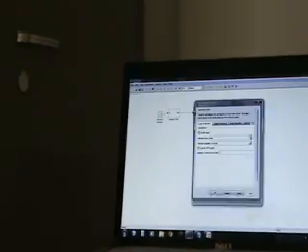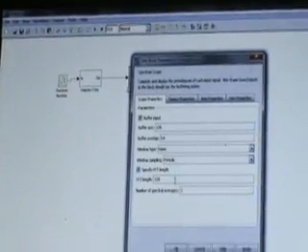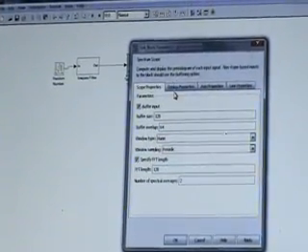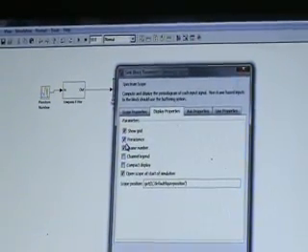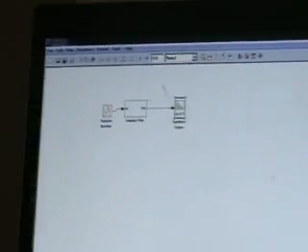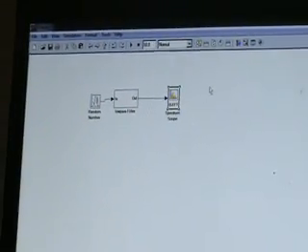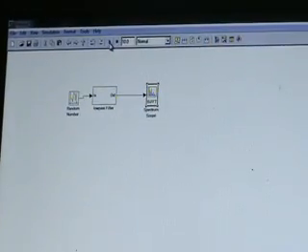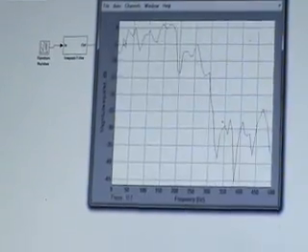Now in the spectrum scope we need to buffer the input, so we click on buffer input. We specify the FFT length, and these are the default values which we keep as they are. Coming to display parameters, we need to change it to persistence, and apply and OK. Now we try to run this filter. We rerun it. Start. Here we run it again. We got an output that we need to change to auto scale.